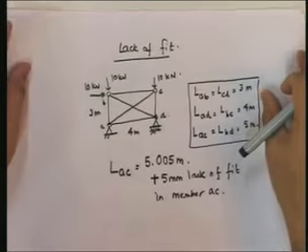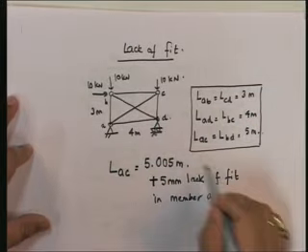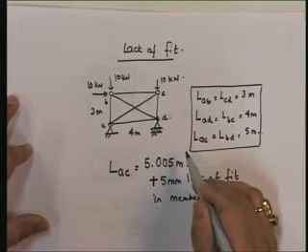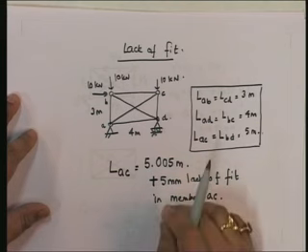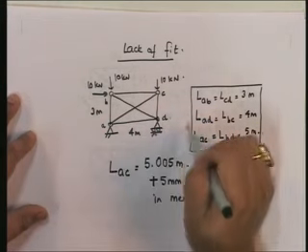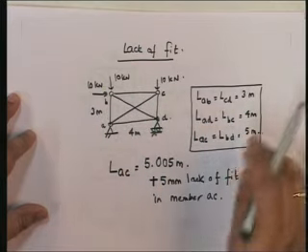So therefore, even if I had this situation, you see this case where I have a loading, in addition to that I have a lack of fit, I can solve this problem in two ways. I can say, well, forget the lack of fit. I'm going to first consider the effect of the loads, find out all the member forces due to the loads alone.